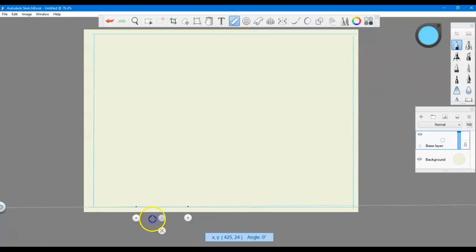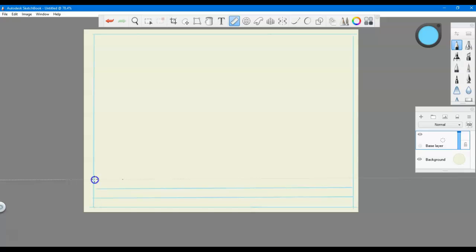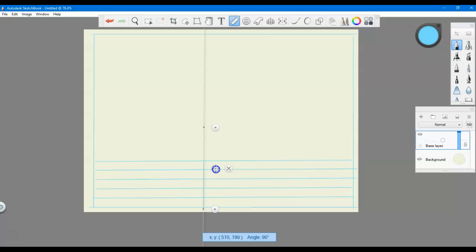Now what we're going to do is we want to draw the text box. Now the text box starts at 510 and then is partitioned at 510, 720 and 930. Height wise, as you'll see in your pack, it'll be 510 and the y-axis will be on 63, then 105 and so on and so forth. Alright, so we bring that across. Everything is in light blue and everything is being drawn on the base layer.